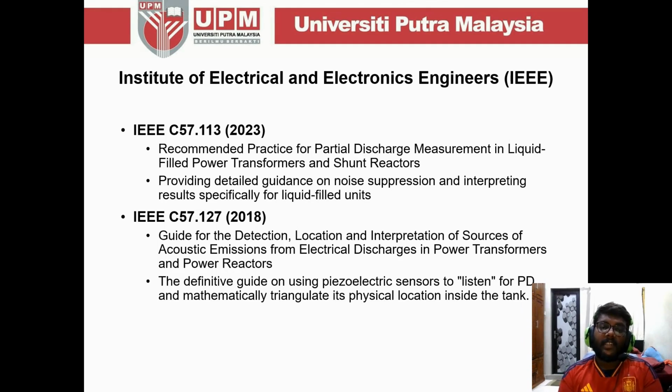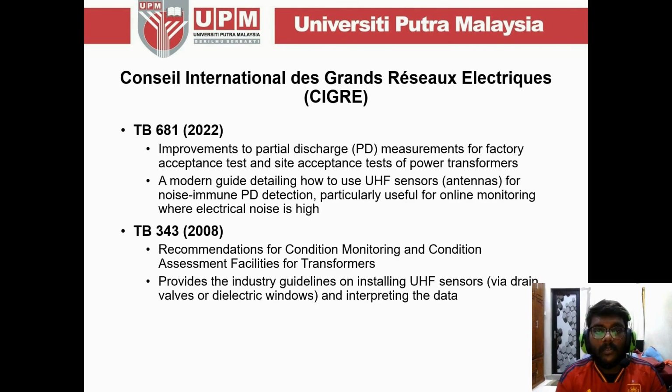It gives us a definitive guide on using piezoelectric sensors to listen to the partial discharge and also mathematically locate the partial discharge inside the tank. Moreover, there is also CIGRE, where they have produced Technical Bulletin 681 to discuss the improvements of partial discharge measurements in factory acceptance tests and also site acceptance tests. And these are all tests to be conducted prior to service.